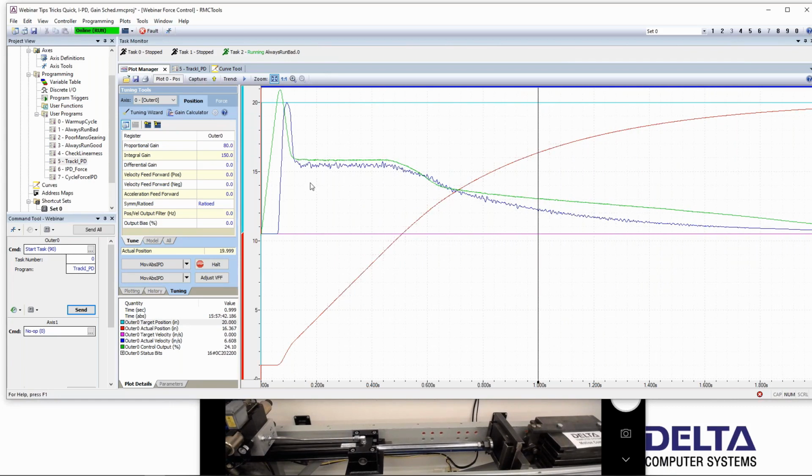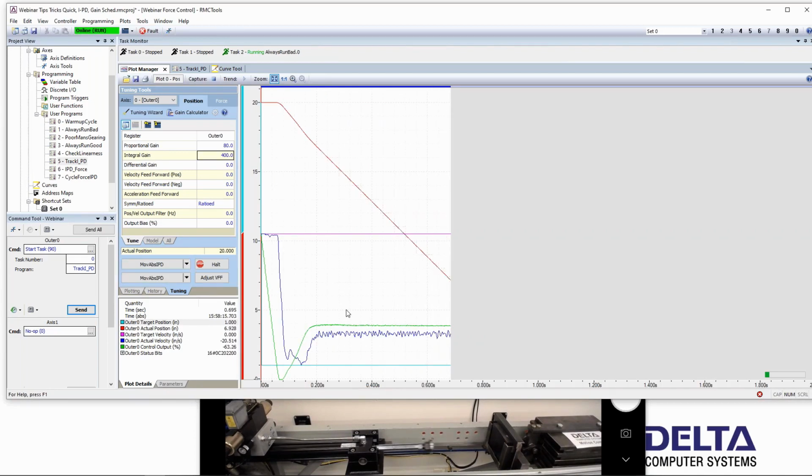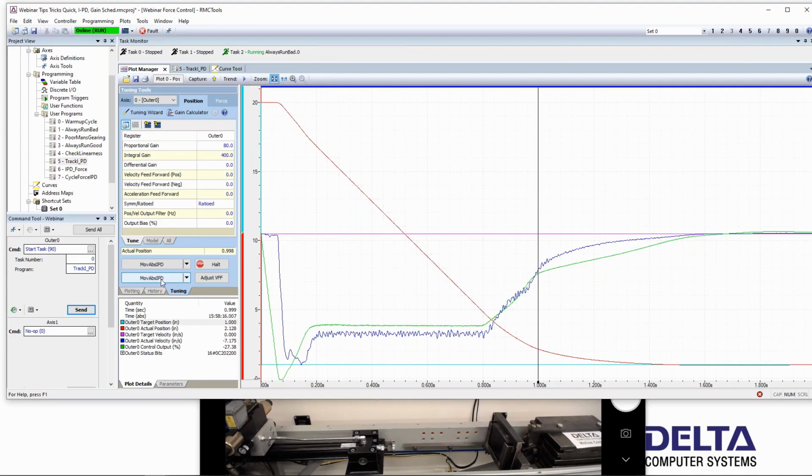Looks like it takes us a while to get in. Notice we're still running this bad system that we're having problems with. So there's a little delay at the beginning before it gets moving, and it does jump on the velocity a bit. It takes I-minus-PD a little bit to deal with the fact that all of a sudden it started jerking. But right now I increased proportional a fair amount. It's taking a long time to get into position. So I want to increase the integral a lot to be able to more quickly get into position there.